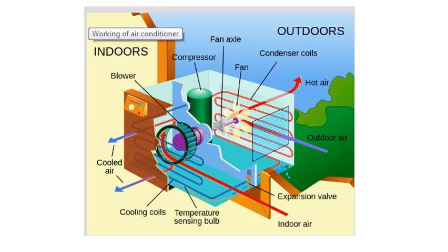As soon as we switch on our air conditioning system, the indoor unit takes in the hot air of the room and blows it onto the evaporator coil in the indoor unit. The refrigerant present in liquid form in the evaporator coil absorbs the heat of the room and turns into a vapor, thus cooling the room. This refrigerant has a lower boiling point, so it can change several times during its refrigerant cycle from vapor state